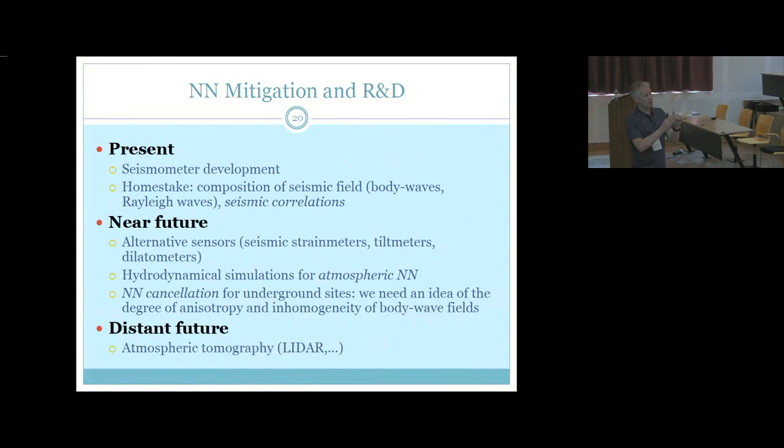So that means there's a trade-off. You have to be careful because the density is another factor that you include again for the gravity noise. So even though you may have lower seismic noise, you will have a boost of gravity noise because of the higher density. And so you have to be a bit more careful about whether you really gain by harder soil. But my guess is probably harder soil is always advantageous in the end, even if you factor in the increased density.